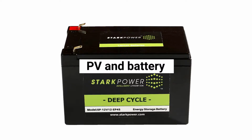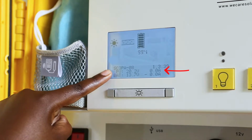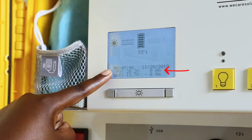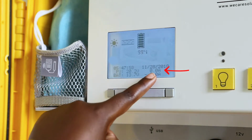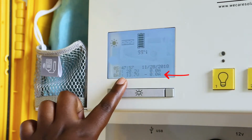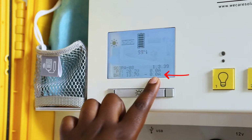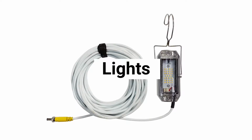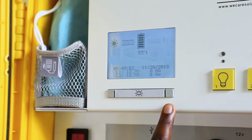PV and battery. The first screen shows what voltage the photovoltaic or PV solar panel and battery are operating at. It shows how many amps of current the PV is producing and how much current the battery is receiving. If connected loads are using more power than is being generated, the battery amps will have a negative symbol before it.